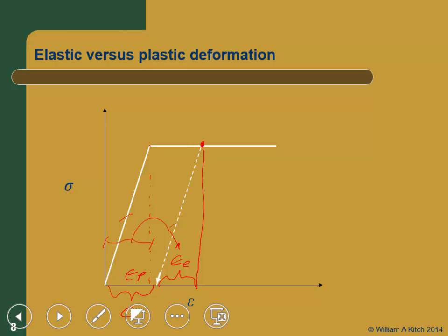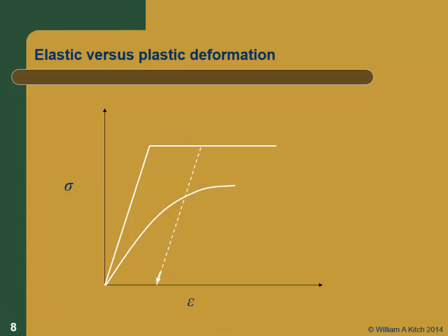I think now I want to erase the... Okay, well here's my nonlinear stress strain curve. So now if I load up to this point, let me mark that point, and now when I unload, I could come down in almost any arbitrary curve. It's very common on these materials to have a fairly linear unloading curve, even though the loading curve was not linear. That's fairly common.